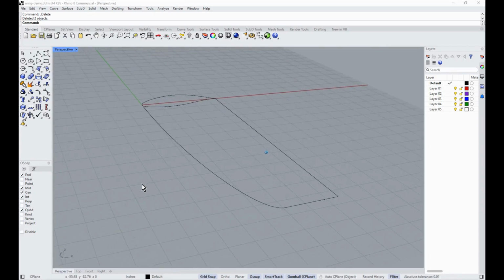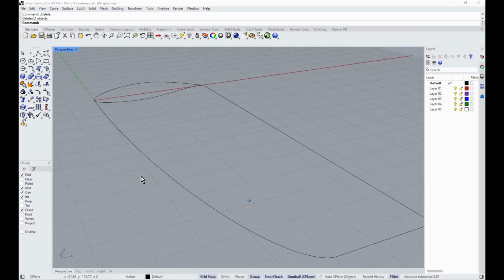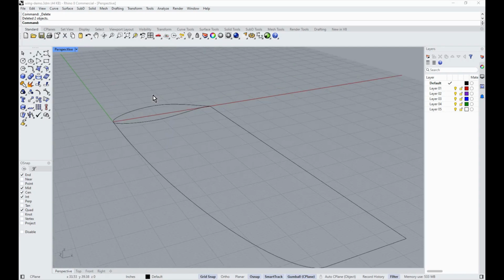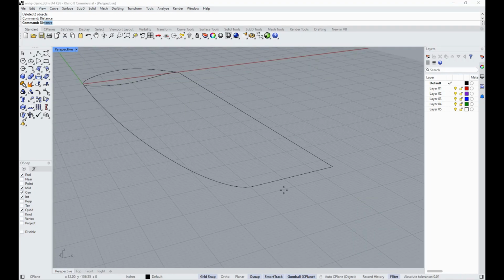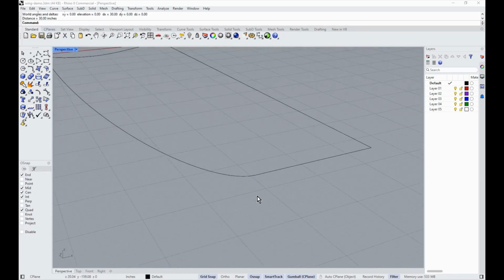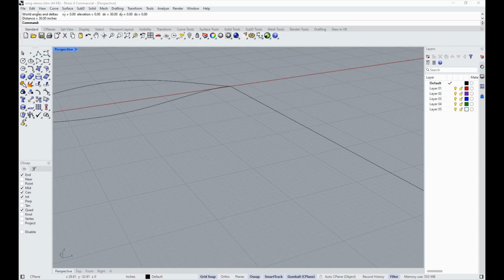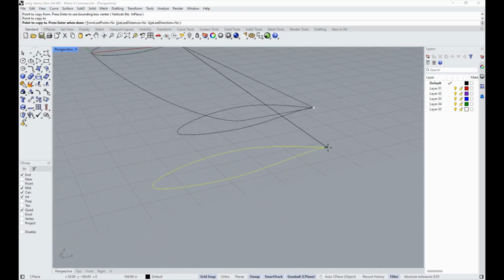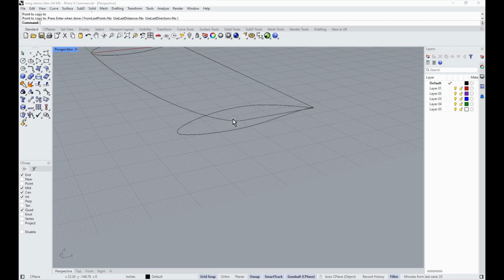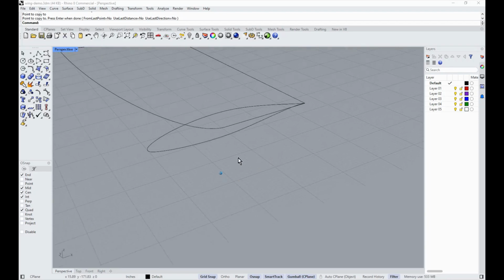Now let's just say we want the same 65-415. I'll show you this way. We could always have made a copy of the 100, bring it over here and so forth. And again, we're at 30 inches on the tip chord, if I remember right. Yep, 30. So I'll show you another technique here. Copy our first airfoil, and we'll bring it over and align it at the tip, just because as the Scimitar goes around the leading edge corner right here, it's a little harder to see.